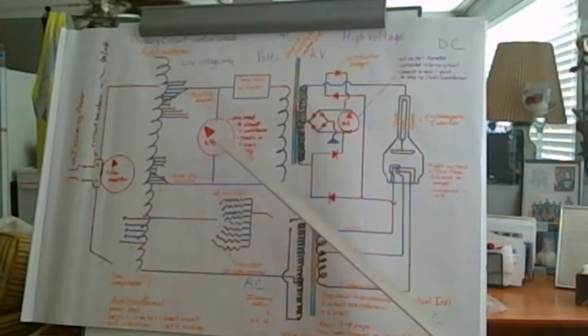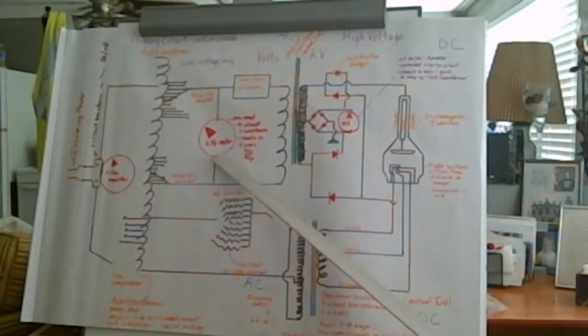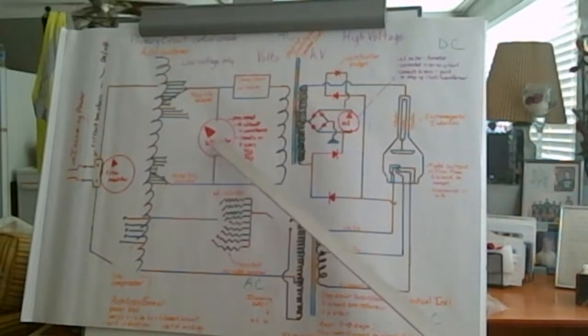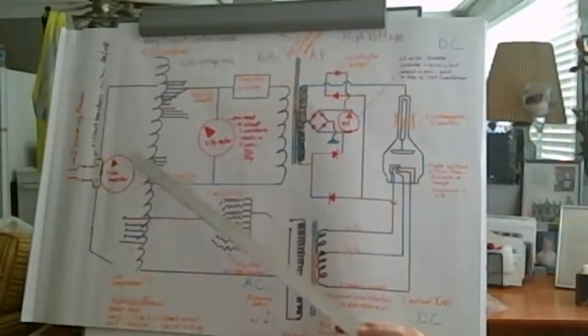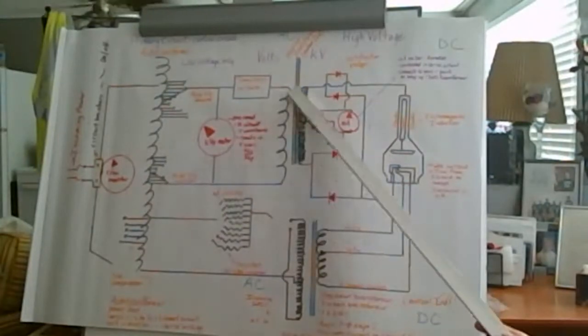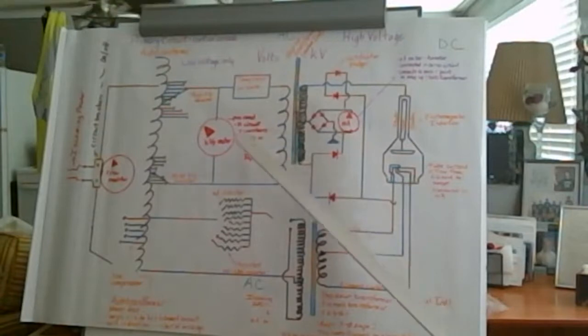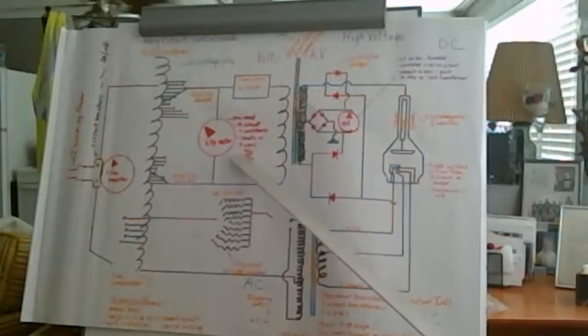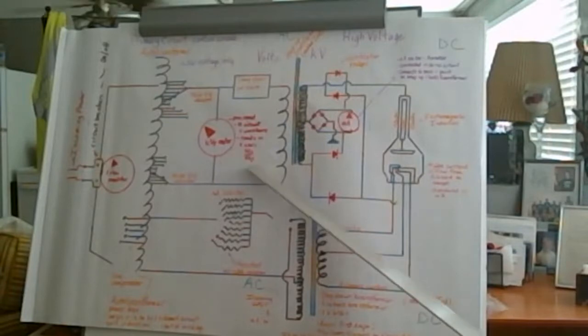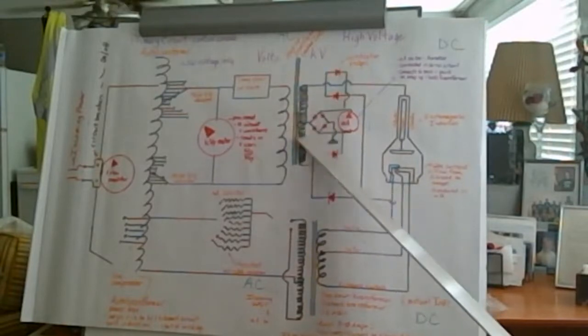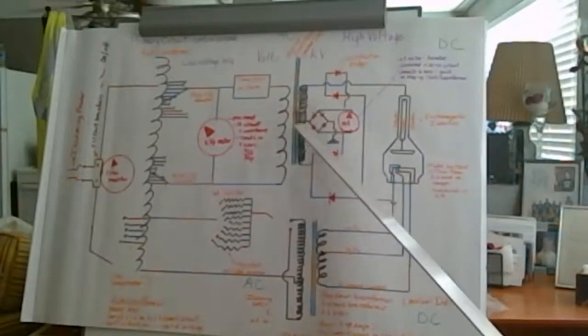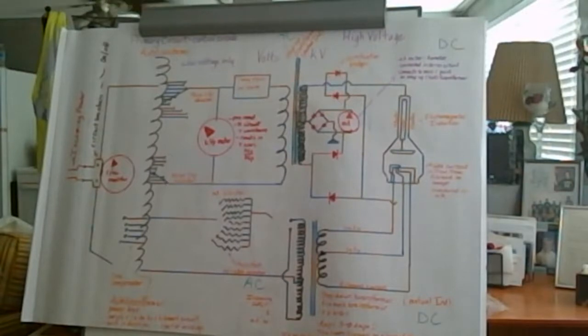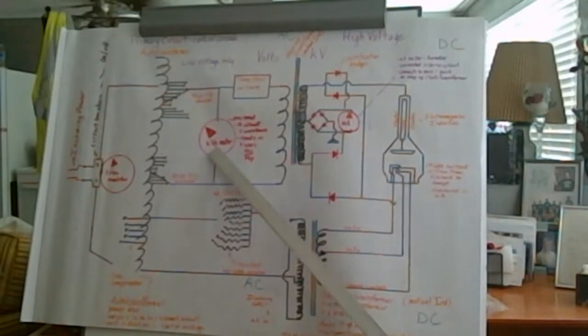The kVp meter actually gives us the information in kilovolts, but that information is read from the auto transformer and this primary side of our step up in volts, and then uses this turns ratio, the turns secondary over turns primary, to tell us what kilovoltage will be at the time of exposure. Okay, so that's very important. This is called the pre-read meter.